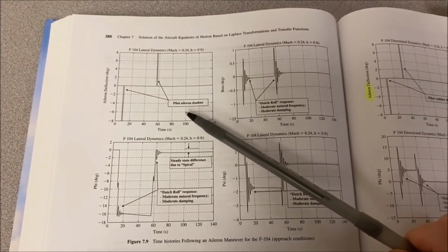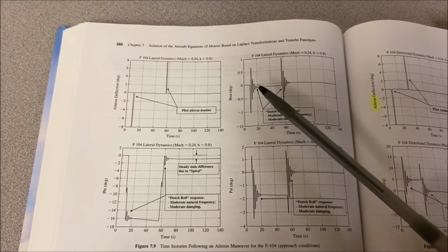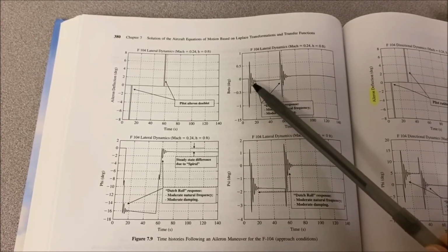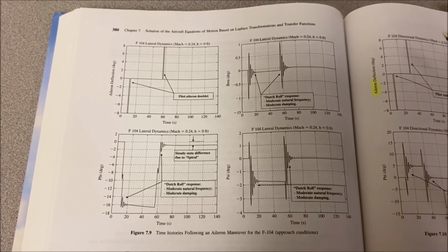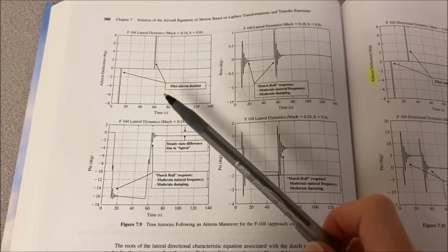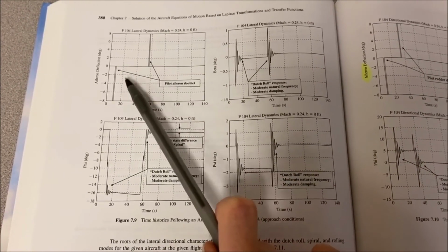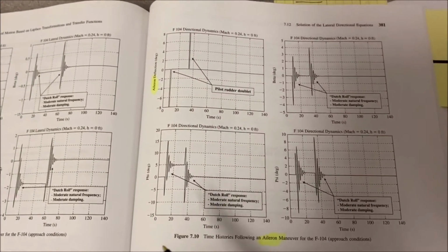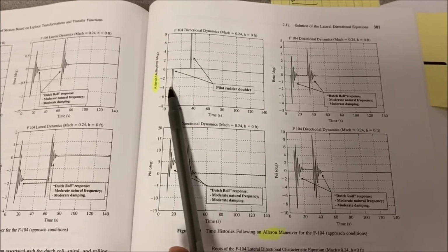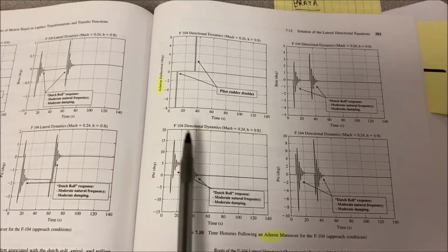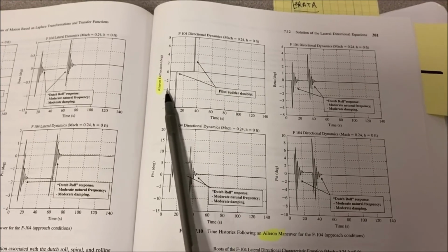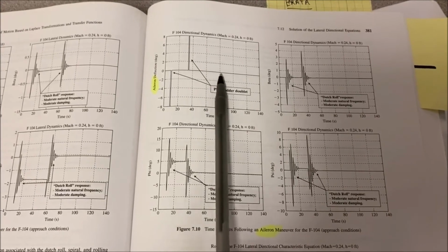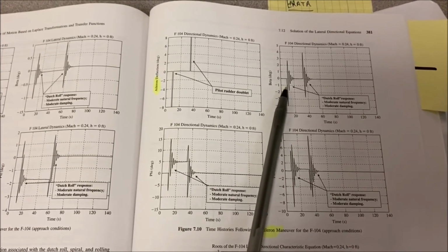So in this case, we're modeling the Dutch roll response. So it has a high frequency and it's stable, right? And then if we do a similar kind of thing where assuming we know a function of how the rudder deflection changes with respect to time, over here there's yet another typo or mistake in the textbook. These should say rudder, okay, as it does here. So here we have this rudder doublet, okay, causing again the Dutch roll response.